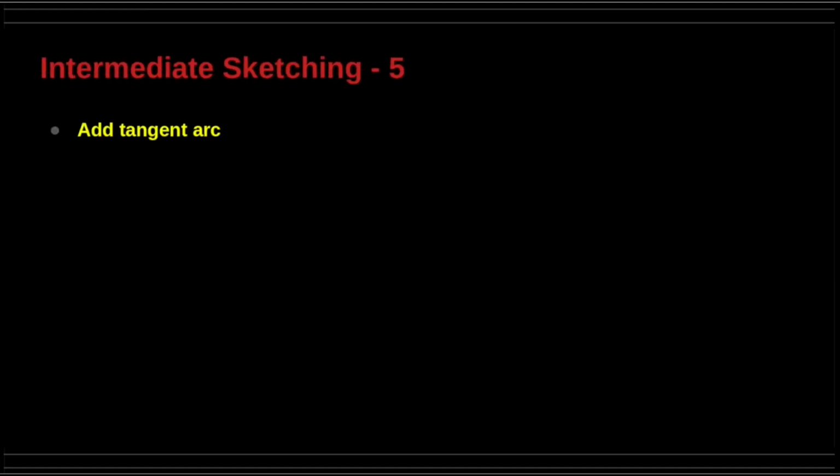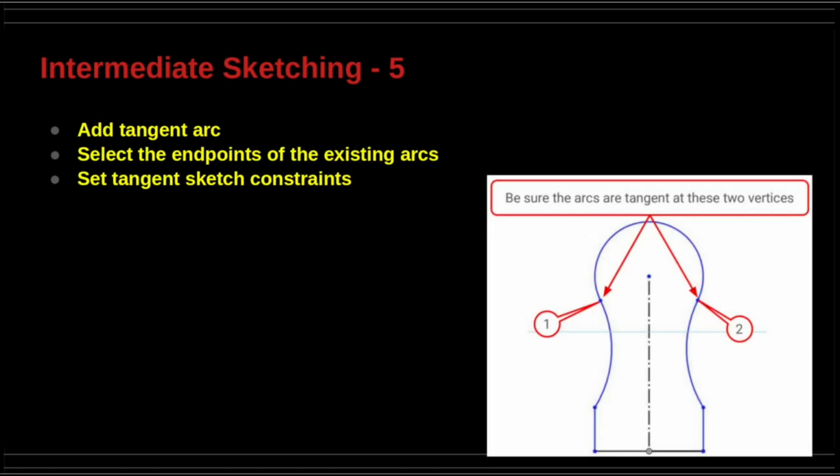Add a tangent arc. Select the endpoints of the existing arcs and set the tangent sketch constraints to complete the arc.